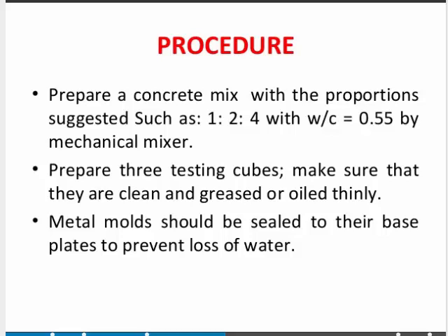It may be 6 also. We should try to cast the cubes, a maximum of 6 in number, as we can test 3 cubes at 7 days and 3 cubes at 28 days. If we want to go beyond these curing ages, then we need to cast more number of cubes. Metal molds should be sealed to their base plates to prevent the loss of water.